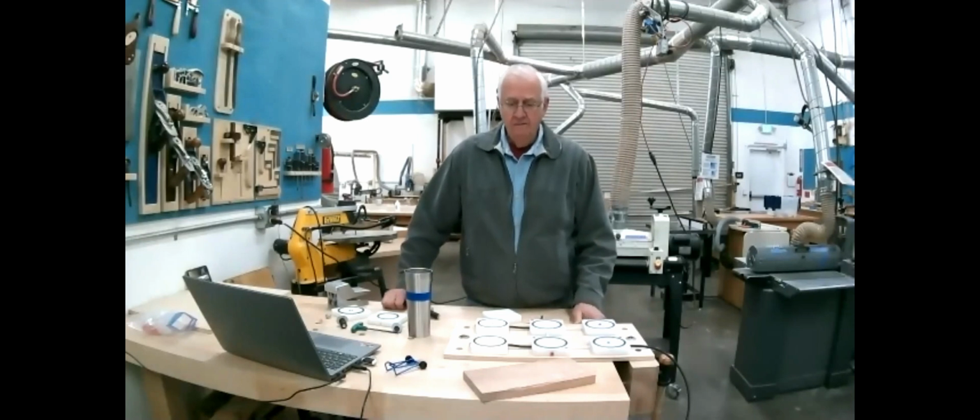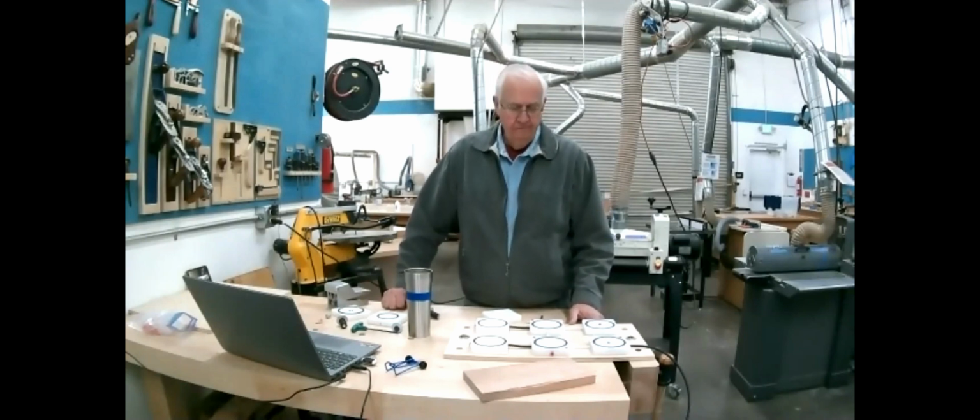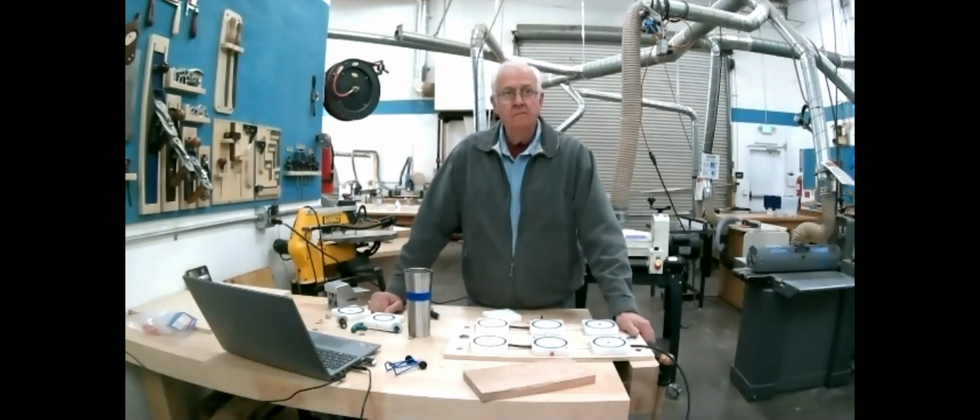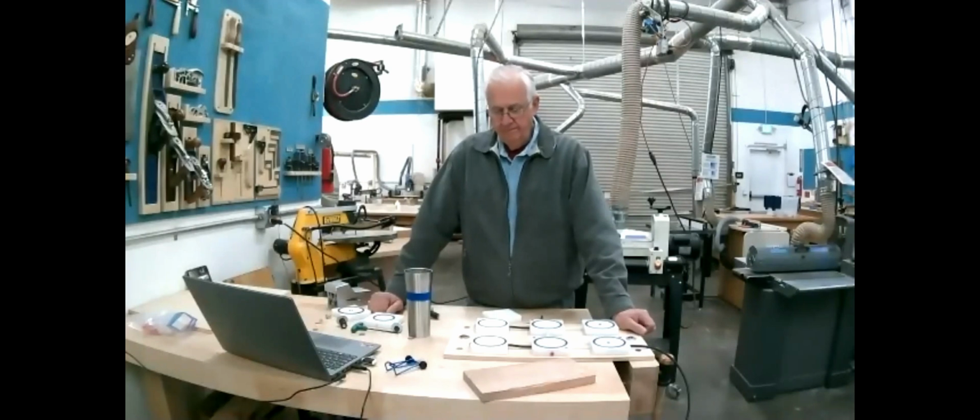If I may, one of the things that is typically done, at least on a CNC, because you really do need that spoil board layer, is there's a version of MDF which is really porous. The word light is in the name of that MDF somehow, and so you basically put a puck system like that below the very porous MDF, and then you're able to hold down your material through the MDF. So the MDF is still there as a spoil board, but it's porous enough that the vacuum actually pulls. You're obviously losing some as you draw through that material, but at least you have that buffer between your puck system and your cut piece. Yeah, I wasn't going to get into that part of it, but yes, you can do that.